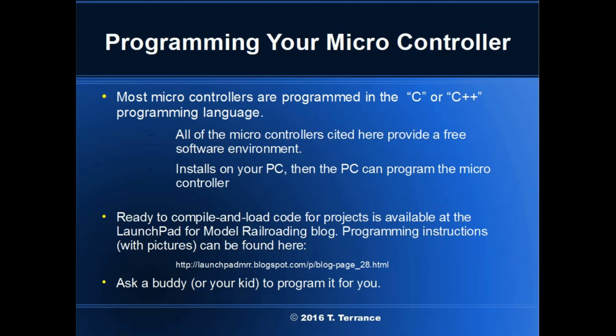You will need to download and load the toolset provided by your microcontroller provider onto your PC. The toolset will allow you to compile code for your chosen microcontroller and then load the machine-readable instructions into your microcontroller. All of the hobbyist microcontroller boards will connect to your PC via USB. You will not need to know the details of where or how to load your microcontroller, all of this should be taken care of by the toolset. If this is confusing to you, have a buddy, or maybe your kid, show you how.